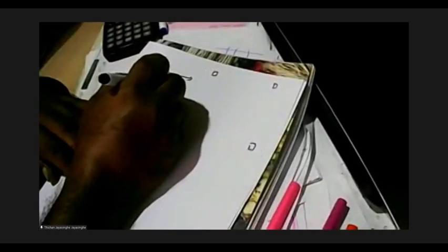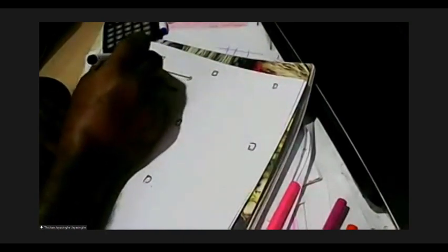Basically, now when we have a two-way spanning slab like this, we convert it to a one-way system. So that means we select the thickness. Generally we select a thickness of about 200 millimeters.